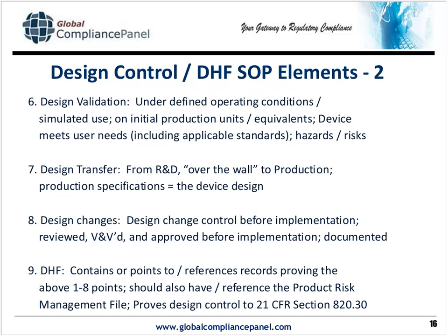The design transfer is the fact of getting all this documentation into the system to drive your production, to drive your ordering, to drive your testing, etc. In fact, basically it's all your device master record documentation, SOPs, training of the SOPs, the bill of materials, the traveler, all those things that would be part of defining how you build the product, the drawings, the SOPs for production, for testing, etc. And then all of this, any changes throughout this entire process from the start date are under an approval sign-off system, resulting in a design history file that covers all these points with documentation or with pointers to where the documentation resides.